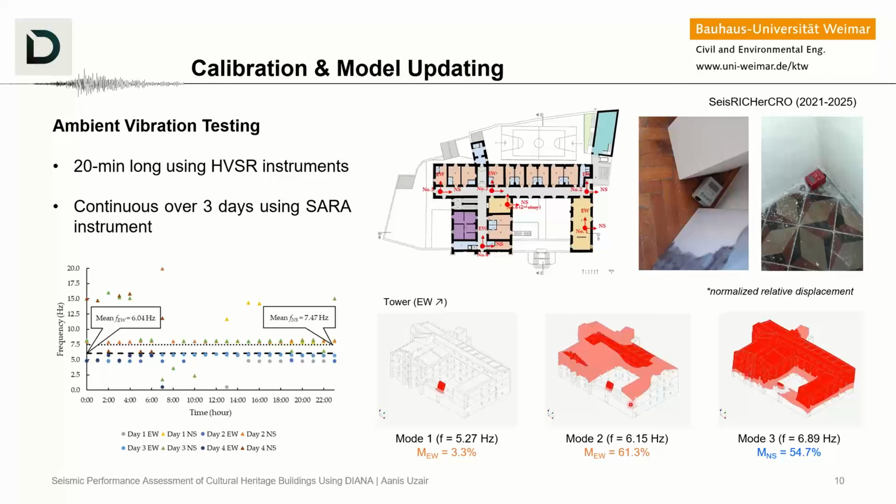And this gives you the information on how the frequencies or the mode shapes from the ambient vibration test can actually look like. And now we have a calibrated model where the frequencies are matching the experimental response, and we can use this model now for further investigation.